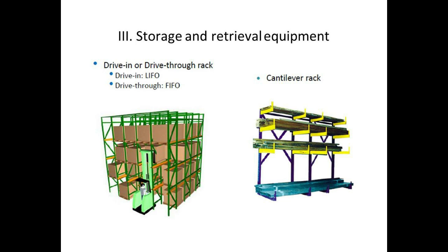While drive-in has no through way. You have to push the material, and whatever you push at the later stages, you can collect first. So these are the two storage and retrieval equipment systems. One is drive-in, last in, first out. Drive-through, first in, first out.